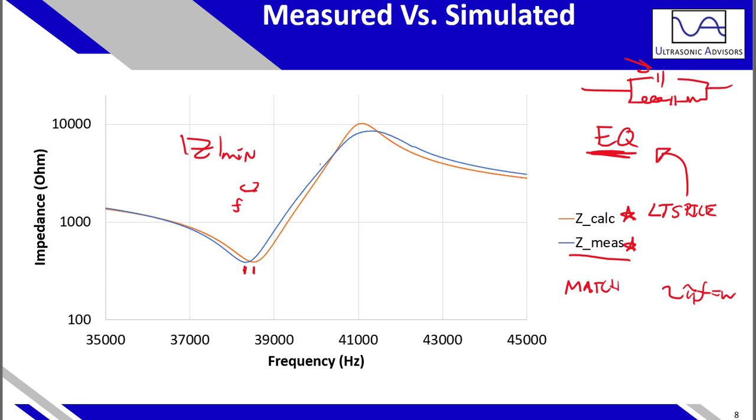That can be due to two factors. But the major factor is that there are approximations done when you are calculating the numbers. So that is with the parallel, so we use many different calculations in order to determine the final equivalent circuit parameters, and due to that factor there's going to be some amount of error propagating through the measurements.